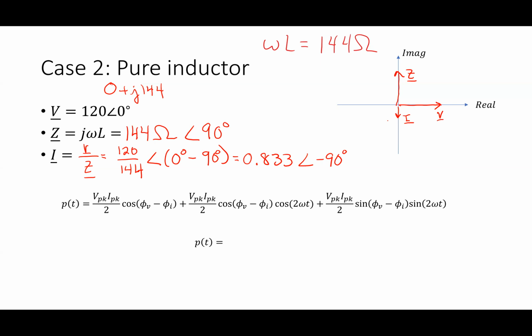The way I always remember that is the voltage has an angle that is more positive than the current, more positive meaning it's farther along in the rotational cycle. I don't bother to remember that. What I really remember is V equals I times Z, so the angle of the voltage always equals the angle of the current plus the angle of the impedance.